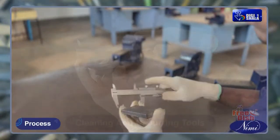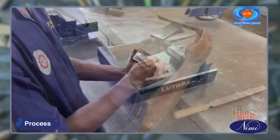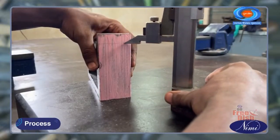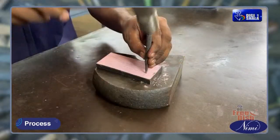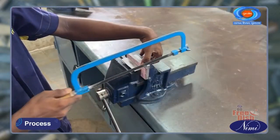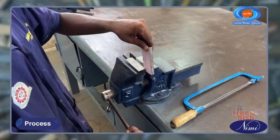Check the raw material for its size. File to flatness and squareness to overall size. Mark dimensional lines as per drawing and punch witness marks. Cut off the material into two pieces, part 1 and part 2, by hacksawing as shown in figure 1.